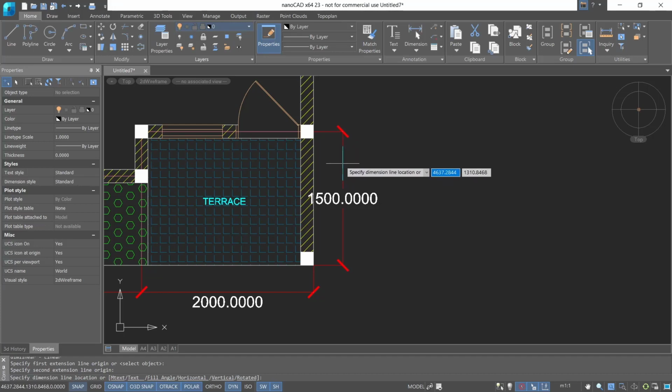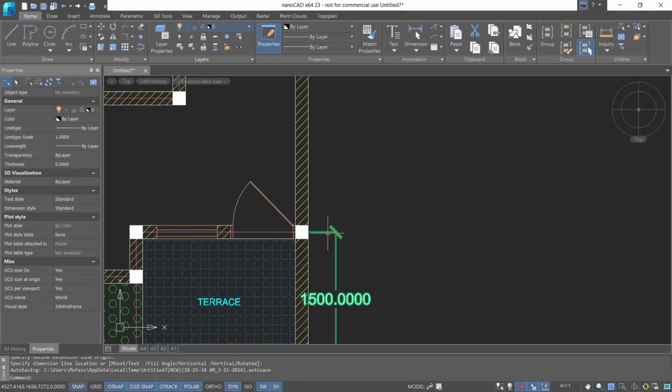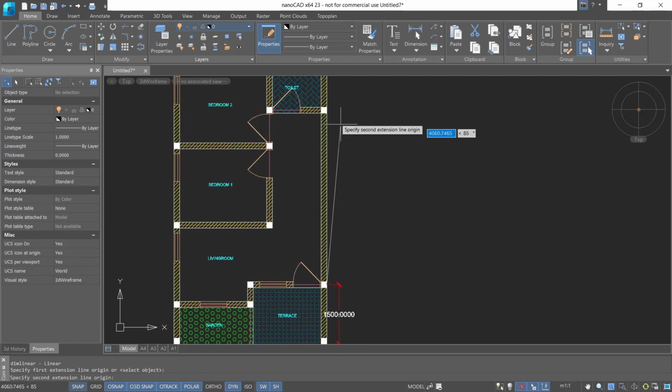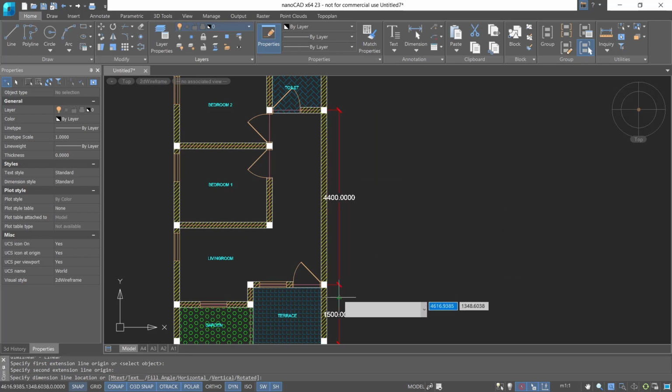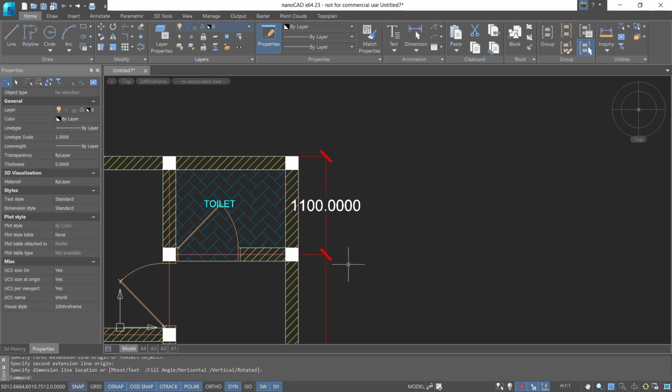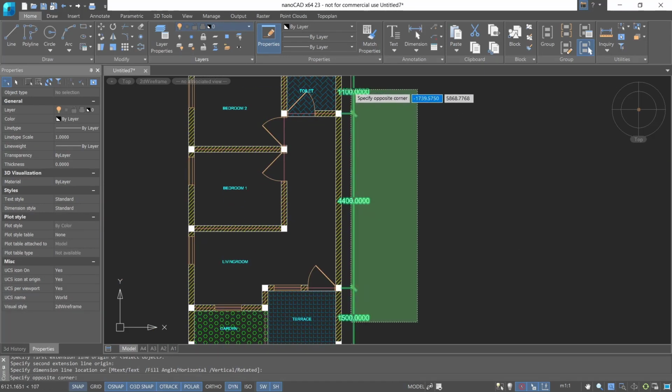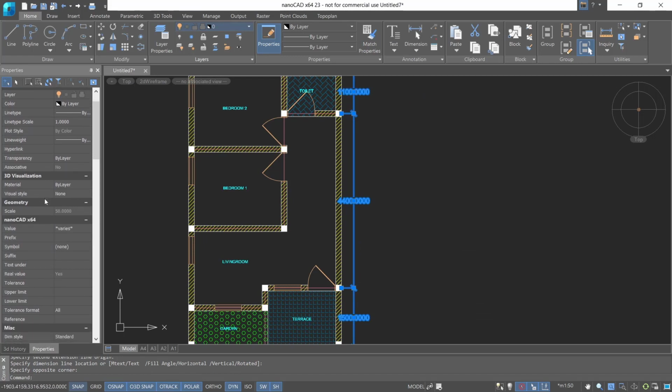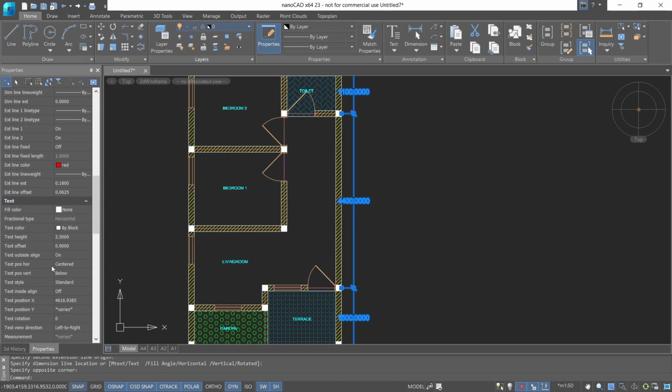And you also can set this option. We create first. Can set into default for the orientation, the dimension text. So click again from this point into here. And then you can select this dimension, go to properties, and click on the text option. In here you can set for the text horizontal. Okay. For the first line extension like this. We'll set into center, and this we set into outside.